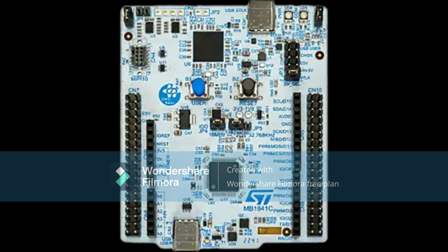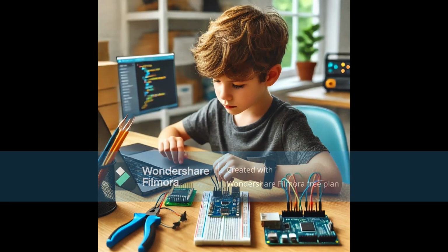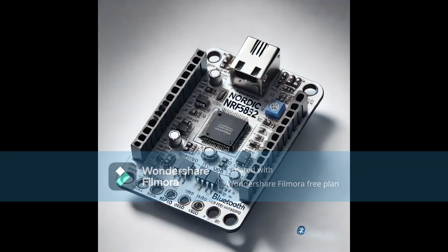Point 2, STM32 hardware setup. Power supply. It is required to power on your device to make it start working. Oscillators. The STM32 embeds an internal RC oscillator, but it is not as accurate and stable as an external crystal. Debug. After programming the MCU, the next step is to debug the code, which means to reconsider it and try to resolve any defect that may interrupt the use of the MCU, and this is realized within a software program called a debugger. While using a software IDE, a debugger is installed by default, but once developing the application of the MCU, a hardware debugger is needed.